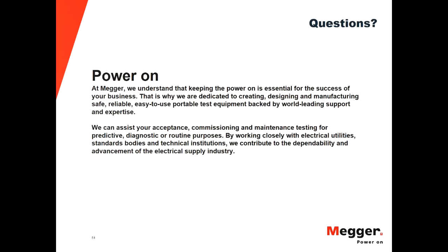And the designer, according to those criteria and those parameters that I mentioned in one of the slides about the aging factor, the service factor, the temperature, all of these considerations, is going to ask for a battery that is capable of covering all of that duty cycle. So, of course, there's a difference there, and the idea is that whatever battery is installed, it's going to be able to handle that duty cycle in the substation.